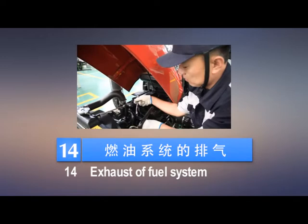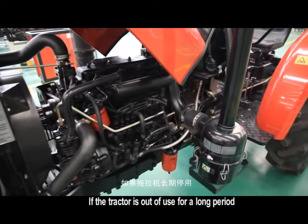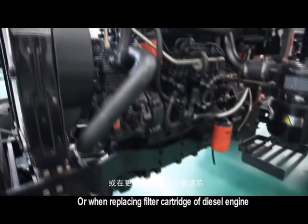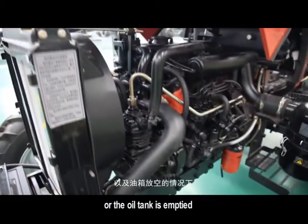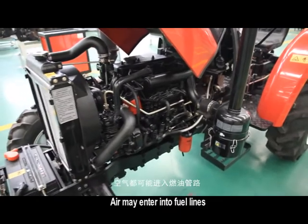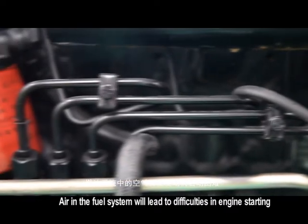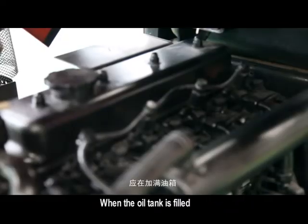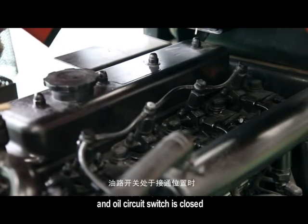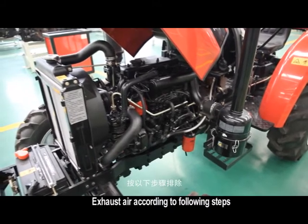14. Exhaust of fuel system. If the tractor is out of use for a long period, when replacing the filter cartridge of the diesel engine, or when the oil tank is emptied, air may enter into the fuel lines. Air in the fuel system will lead to difficulties in engine starting. When the oil tank is filled and the oil circuit switch is closed, exhaust air according to the following steps.